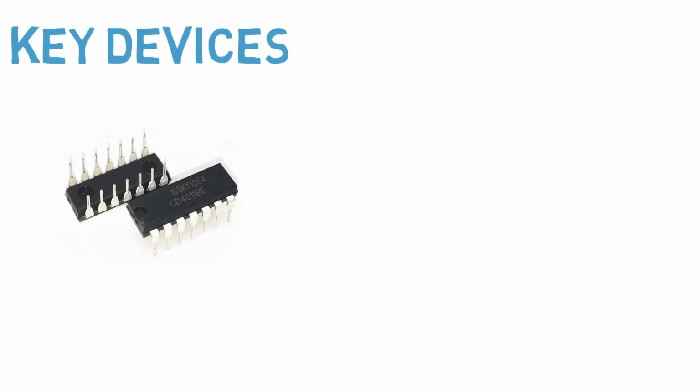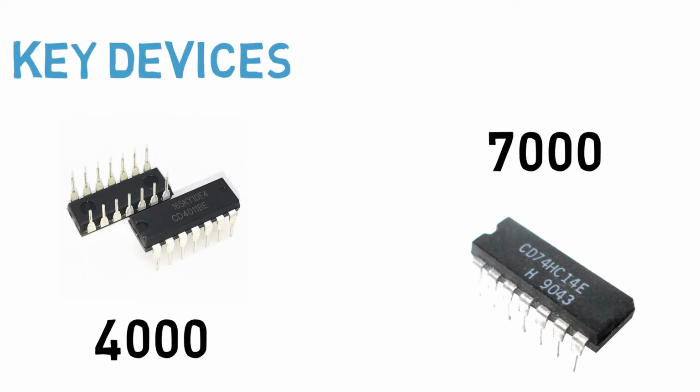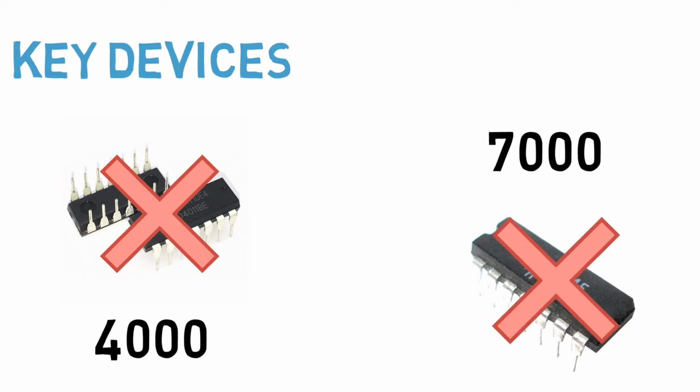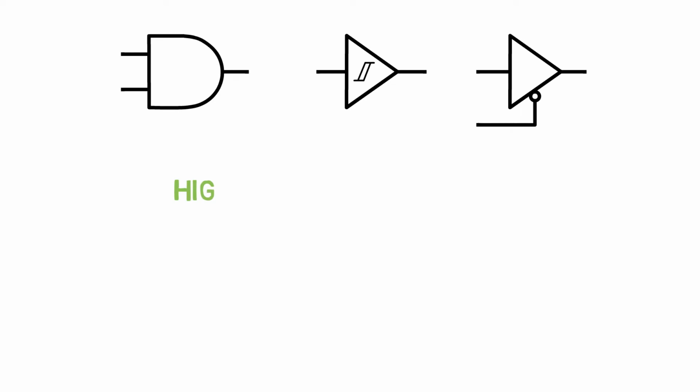When you look at logic device circuits on the internet, you'll see many of them use obsolete 4000 or 7000 series logic from the 80s. While these devices were undoubtedly useful and paved the way for modern electronics, it is my view that these ancient devices have no place in modern circuits. You see, while we have always needed functions such as ANDing, Schmitt triggers, and line drivers, these devices usually have high propagation delays and make them unsuitable for most designs.